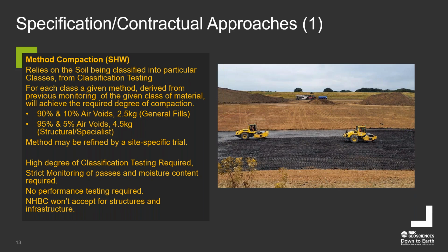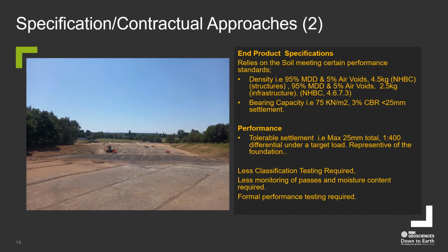Unfortunately, most clients, consultants, or regulators are not so trusting, and they'll require some form of testing and proof that you're meeting the required standards. This relies on undertaking tests during the job to ensure that you're either meeting the density requirements needed to deliver the performance on the site, or directly measuring the qualities you're seeking on the site in terms of bearing capacity and settlement.